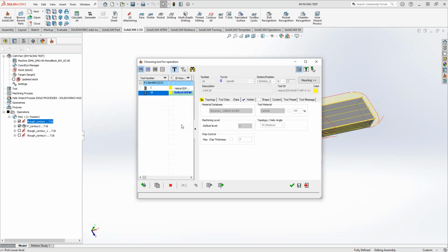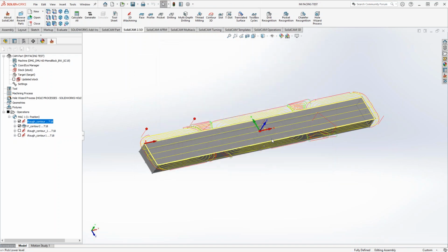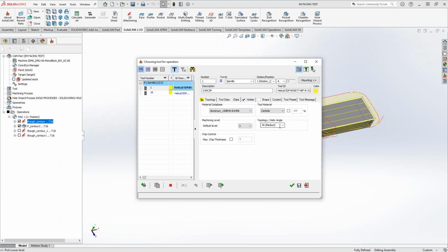While Kevin's copying this tool, if in that same bar you saw a yellow color, then it's mid-efficiency. It's a good use of the tool, but it's not fully optimized. When you get that green color, that's the best use of the tool. It's figured out the best way to use that tool, feeds and speeds, the step down, all that material engagement is going to be used to the best of the ability of that tool. So when you see that green color, green means go, basically. It's a really good use of the tool.